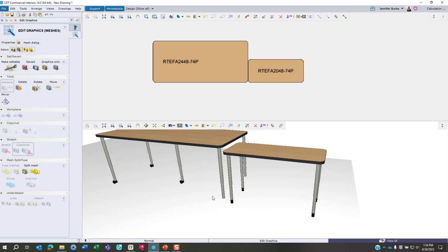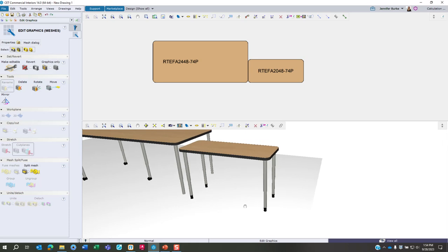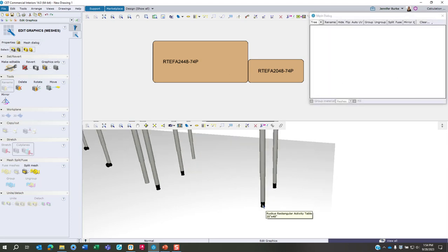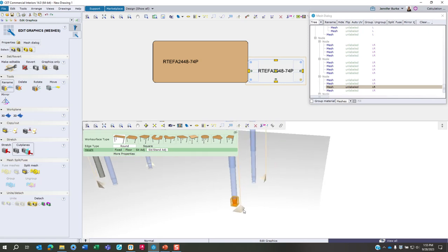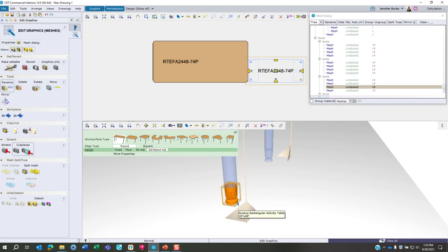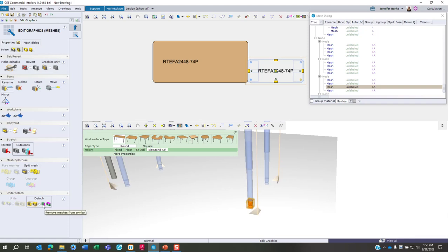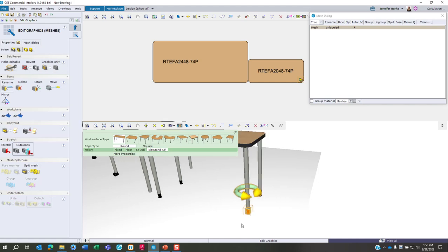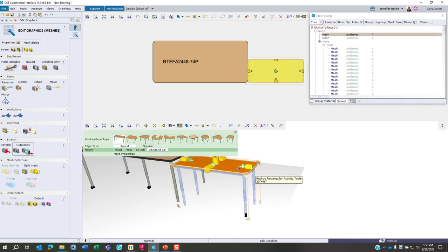Once the casters are deleted, we are going to detach one of the glides from the other table. Open the mesh dialog box and select one part of the glide. Depending on how the 3Ds were created, you may have to select multiple meshes or the entire node. In this instance, I just need the one mesh. On the left-hand side, I'm going to click on Detach. Now the glide is separate from the entire table. The next step I would recommend is just deleting the table.